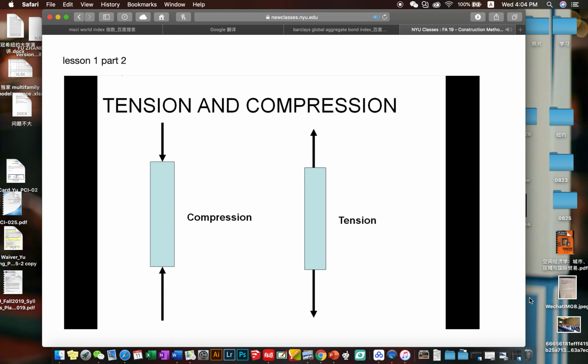Two other concepts to introduce you to and to get out of the way now are tension and compression. And these two act interchangeably and together. If something is strong in compression but bad in tension, it's good for certain uses but not others. What materials out there are good in compression, basically? What materials are hard to reduce their length when you push on both ends? So you think of things that are very stiff, very hard, very rigid, things like concrete, bricks, steel, can be good in compression. Others are good in tension.